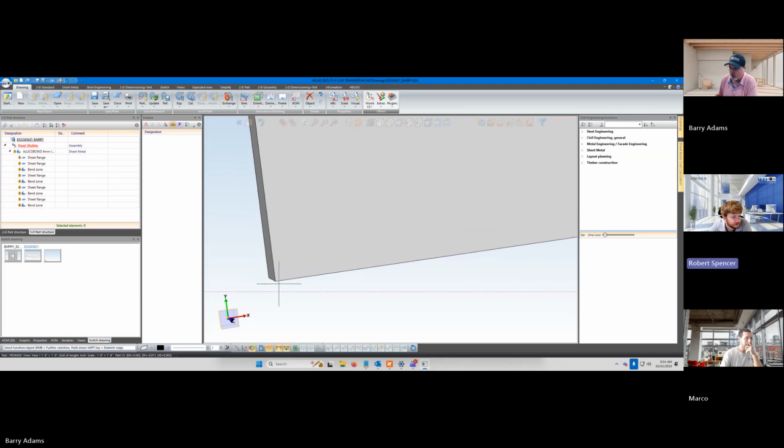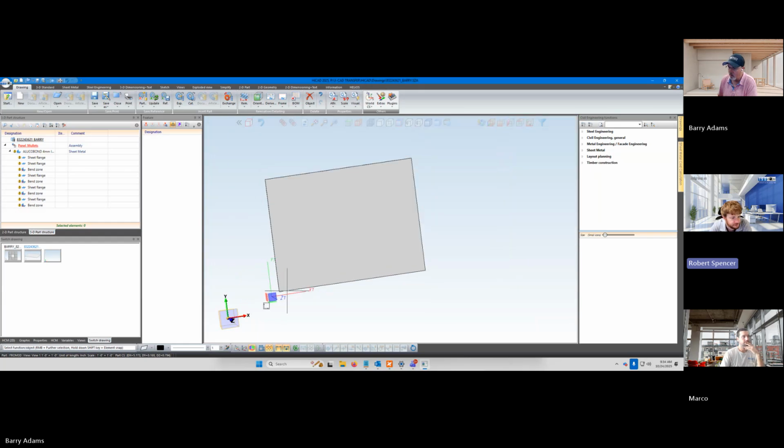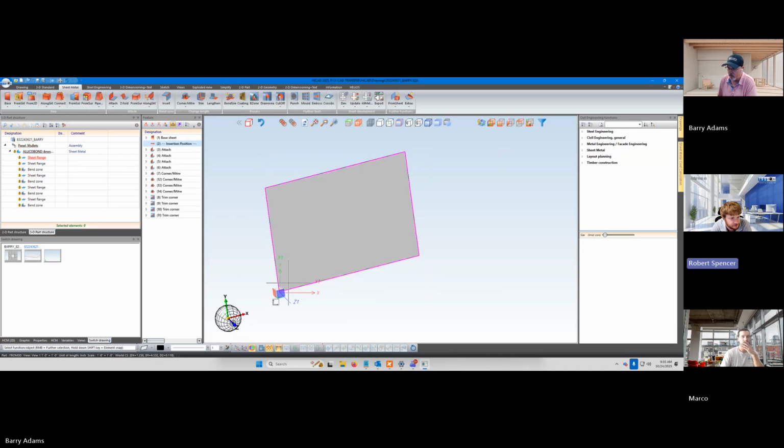Okay. All right, now switch back to your world for a minute. At least on my computer, you'd have to toggle it a little bit to get it to update. So if you hit your world system for a minute, okay, now go back to your part system. So drop down under World CS and say Part CS. World CS. I'm going to hit it again. And then under this one, so activate the assembly.